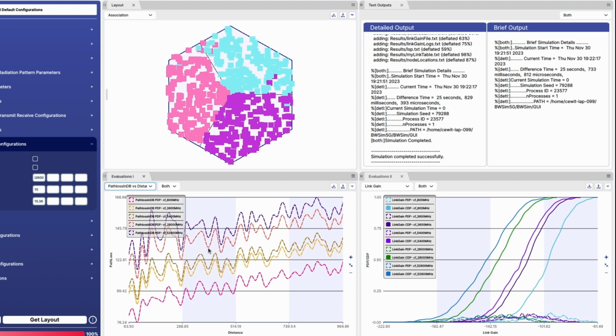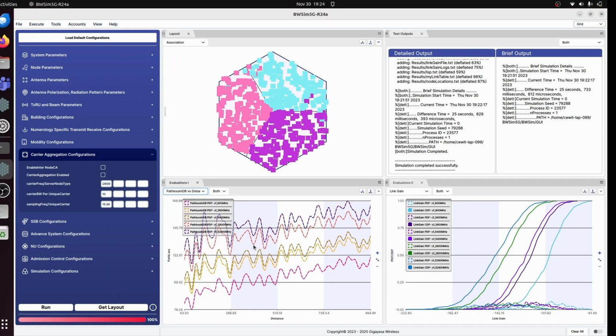And these low wavelength signals cannot diffract or bend around the edges of the scatterer, thereby increasing the path loss. Also, signals modulated by higher carrier frequencies are more susceptible to absorption than those modulated at lower carrier frequencies. With these two observations and inferences in mind, we can move on to the next stage of experimentation.